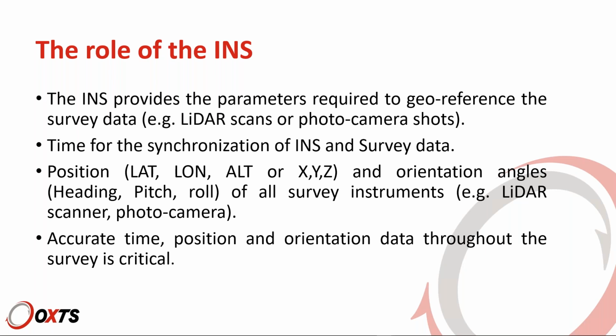Orientation angles, heading, pitch, roll for the drone itself, and hence for all your instrumentation. Obviously, having accurate time, position and orientation throughout the data collection is critical, so the INS needs to provide also validity and integrity of the data.